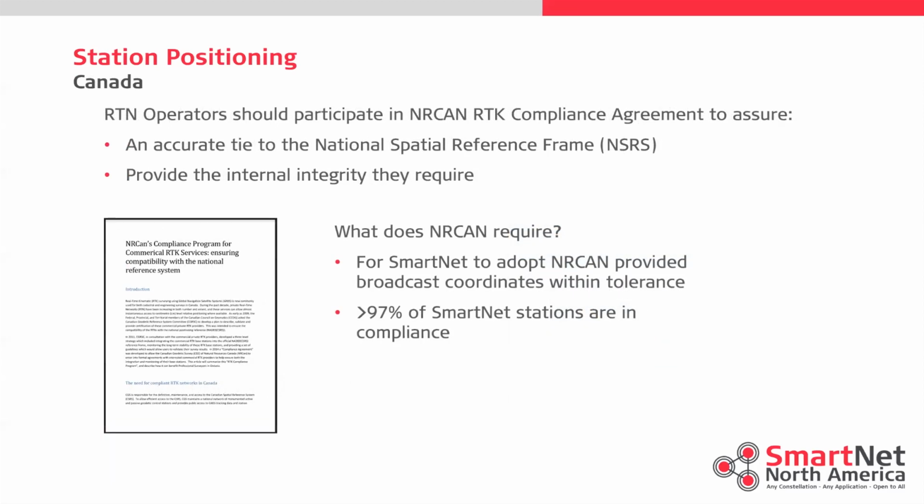Outside of the US, we also have Canada. We've signed an RTK compliance agreement with NRCan. This was signed by a number of different RTN operators. And again, this is to provide an accurate tie to the NSRS in Canada, and also to provide the internal integrity required. NRCan traditionally requires us to adopt their broadcast coordinates, the coordinates that they derive, within a certain or set tolerance. So 97% of the stations for SmartNet are in compliance, but currently we're in V6,